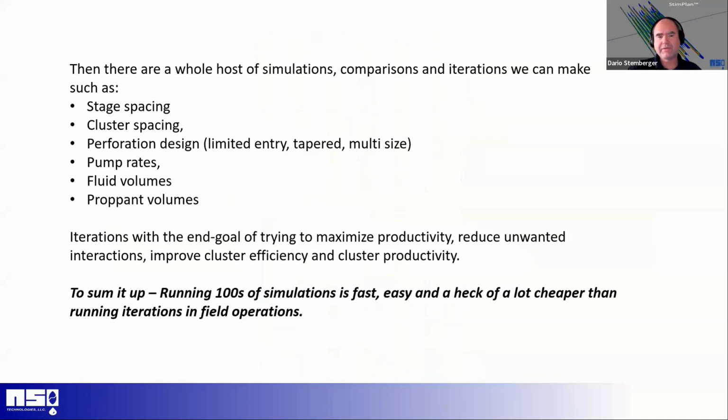And then the nice thing with frac models is that you can run multiple iterations very quickly. You can change so many different variables to help you understand how those variables might alter the final frac geometry. And when you get wells that don't produce the way you want them to, you can look at these things and zero in. So what we did zero in on was that 5 of the wells had cross-link fluid used, and it connected both water above and below. They did some water analysis, so we know that they got immense frac heights.